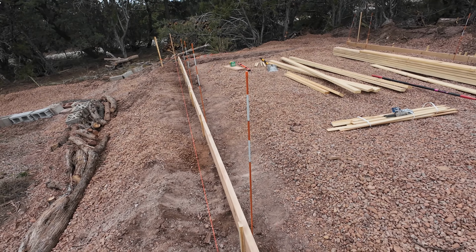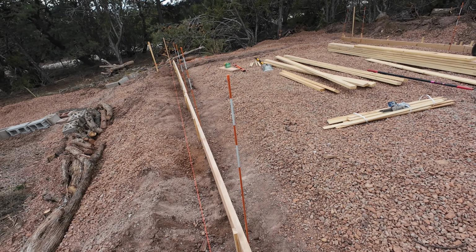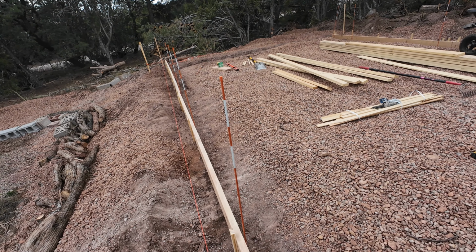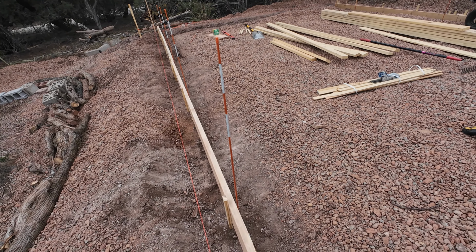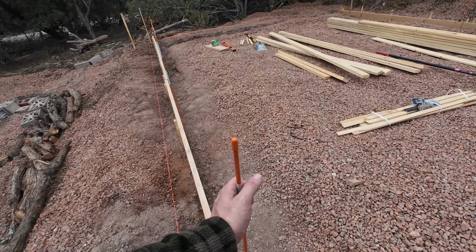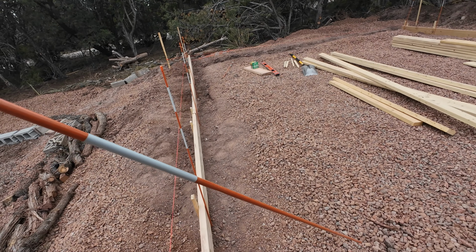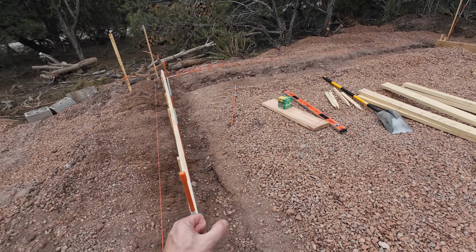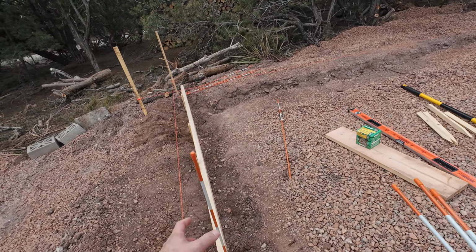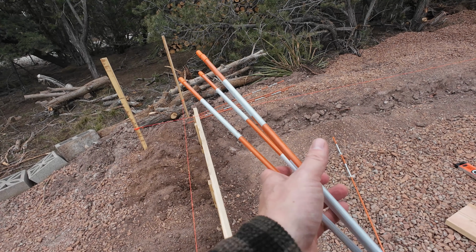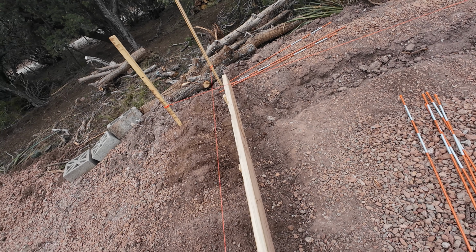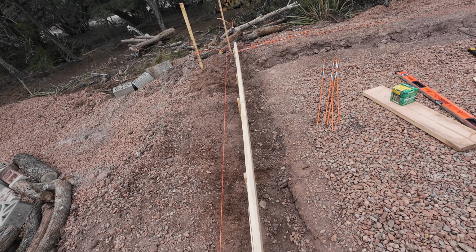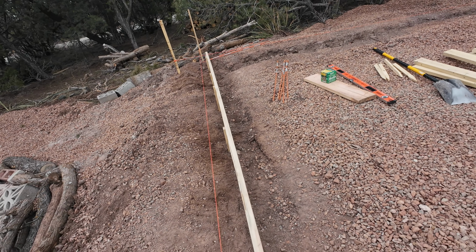Okay, so now I have this board face concrete form in place. It's definitely not perfect, but it's a lot better than if I had done it myself with a measuring tape. And I can come along here. I no longer really need my string. I've checked that the form is level, pretty level. And I can kind of use the board face. I'll go ahead and stake out the board face though with the tilt on the GPS rover and show you what that looks like.